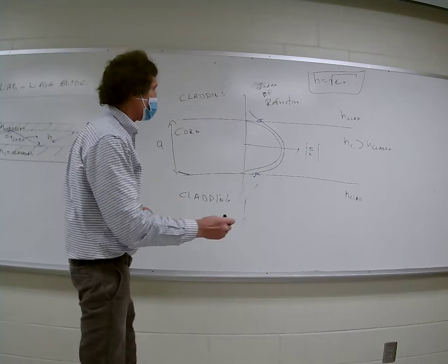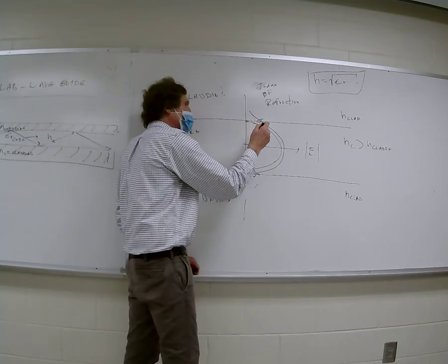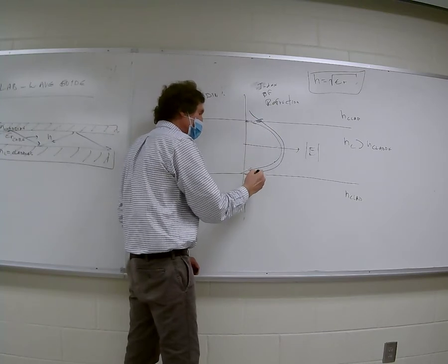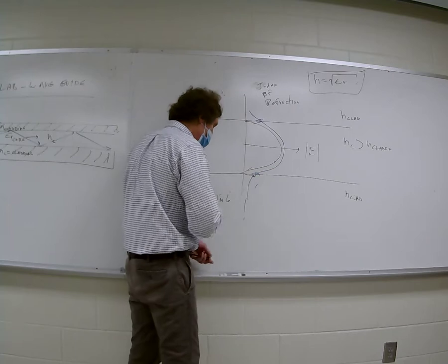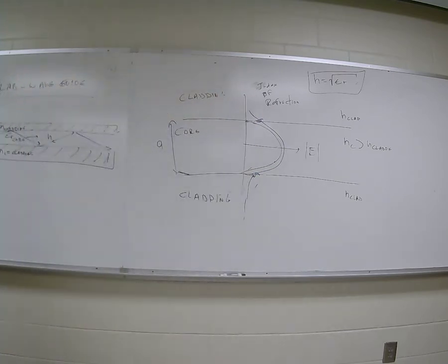Here's what really happens. This thing would be a half wavelength if it would short out. Actually, it doesn't short out exactly. It gets small, but it doesn't go to 0. And what happens out here, you're going to get modes propagating in this direction, that direction, that just damp out. They're evanescent modes.